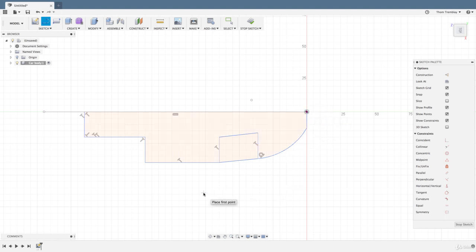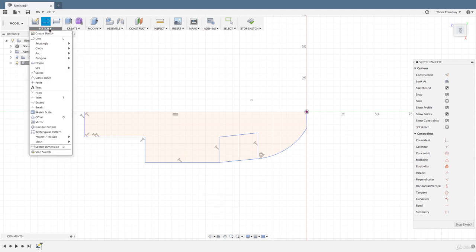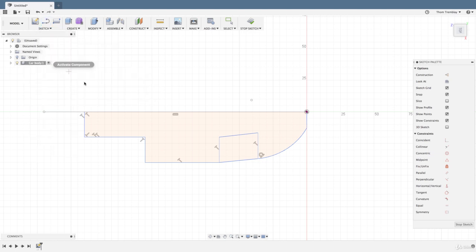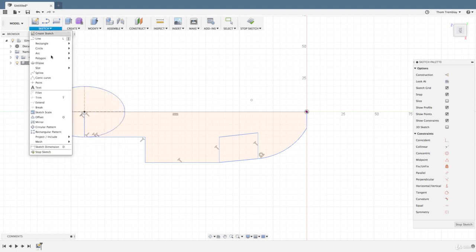Now I need to do some cleanup of the geometry before I think about refining the sketch with dimensions. Before I do that, I need to add one more piece of geometry. To give a little better shape to the nose, I'm going to add an ellipse to the sketch, selecting the first point and then the two axis points. Then I can trim that.